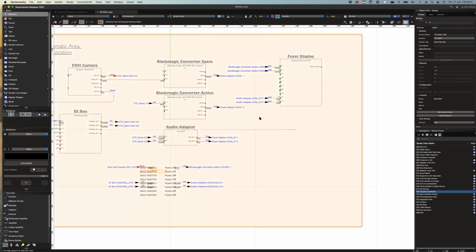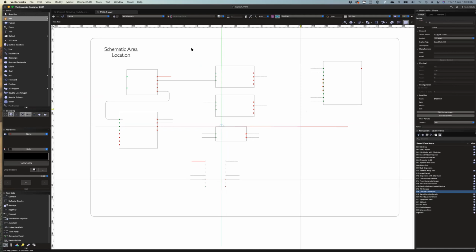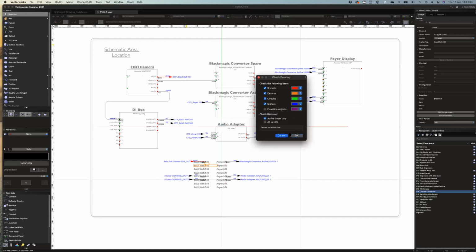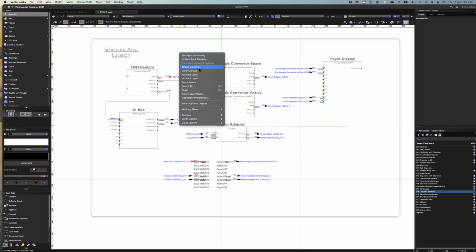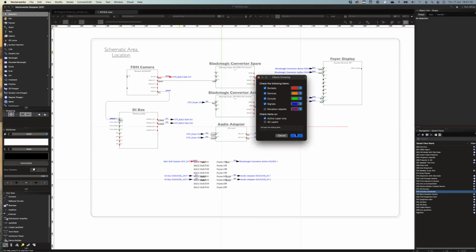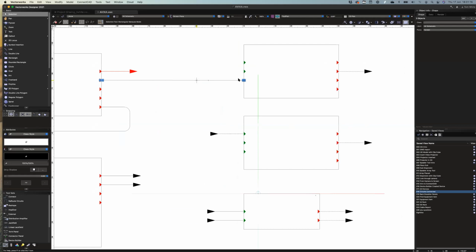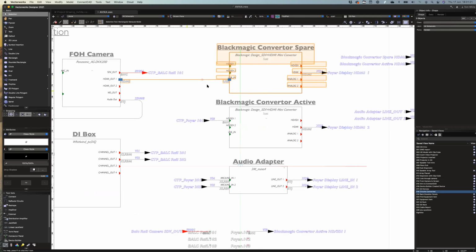I've numbered my cables. Before I create the equipment items and we start looking at how to create these racks, I'm just going to right click into the space and just do check drawing. And I'm going to ask ConnectCAD to basically just check everything is correct on here. So let's do that again, click OK. And it's just going to make sure everything's okay. But as you can see, it's picked up our deliberate mistake over here. It's gone, you can't plug a HDMI cable into a USB. It's just not going to work. So it's highlighted that as a problem. So I'm going to delete that.